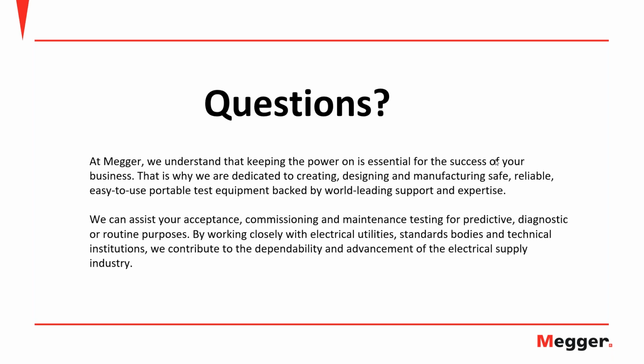Let me jump in on that also. The D877 method of testing, like he said, has the flat electrodes at a specified gap, but the oil is also stationary. In the 1816 method, you use the mushroom electrodes at either the 1 or 2 millimeter gap, but that oil is also circulating through while they apply the voltage.